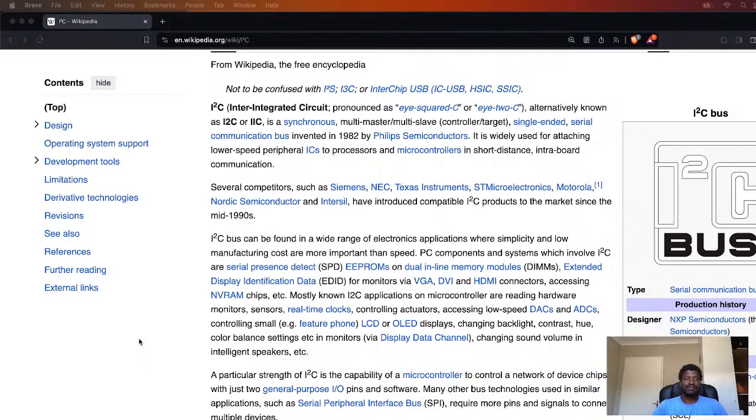So it's very easy for whichever device sends a start, we'll get to this, whichever device sends a start signal or a start condition in I2C, from that point onwards is regarded as the master. So you could have multi-master configurations. You could have 2 devices and they could swap which one's master, depending on the operation that you want.